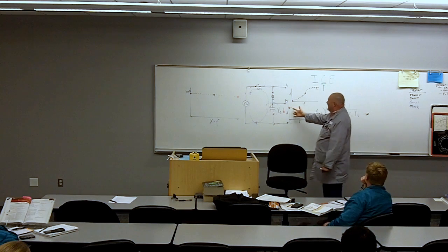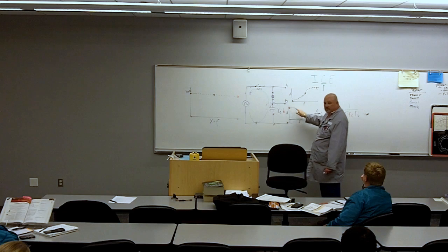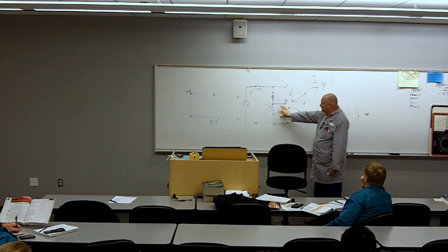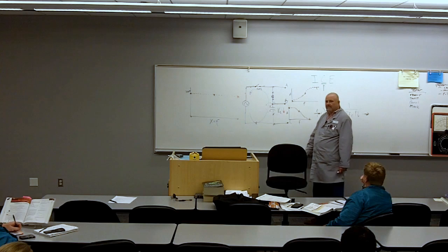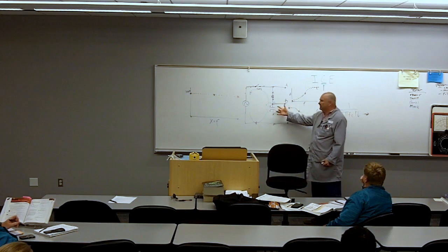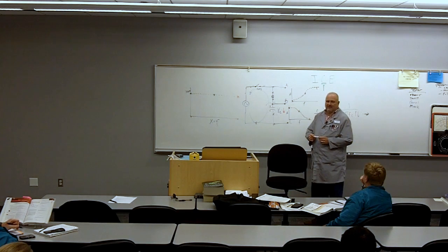For a pass filter, do you see how I'm passing that high frequency? Or, excuse me, low pass, what am I saying? Low pass filter, see how I'm passing the low frequency? Where do I have my output connected to? Across my capacitor. Across my capacitor, what's another way of saying across my capacitor? In what configuration with my capacitor? Parallel, thank you. And that's key.